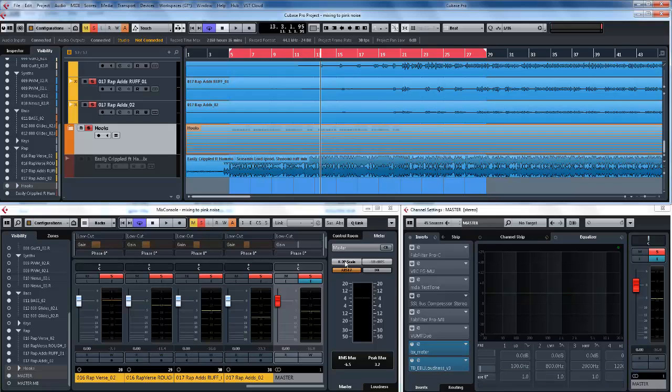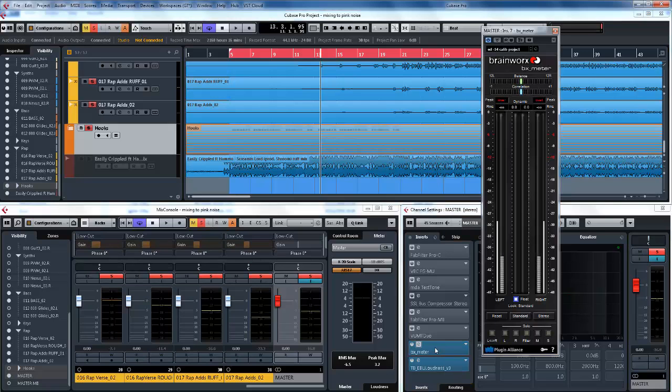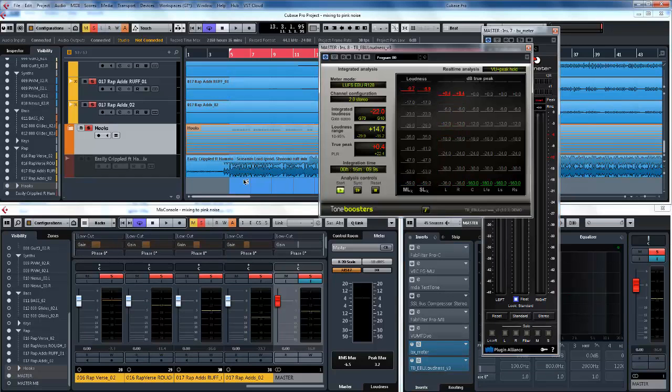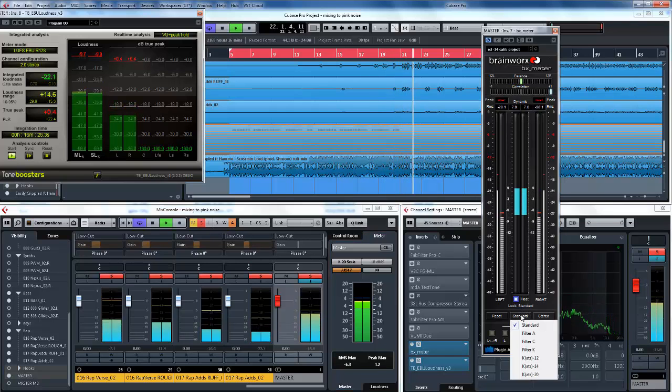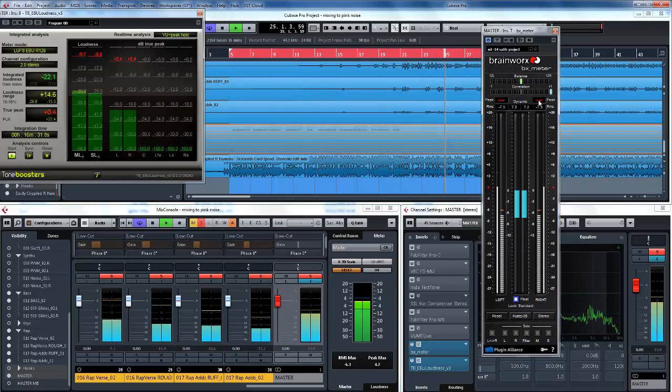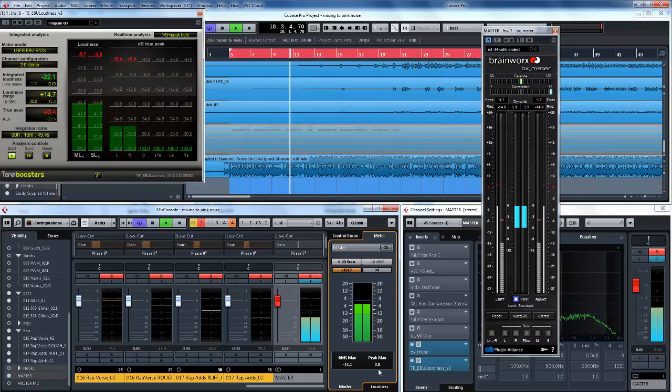Let's first add K20, AES17, PPM meter. I'm using this as the K scale reference, BX meter, loudness meter, and let's play now. Easy. Wonderful. Look at this. And our readings here, because I'm in standard mode, I'm in digital mode, are in dBFS. Let's go to K20. Best kept secret. Eerie, isn't it?